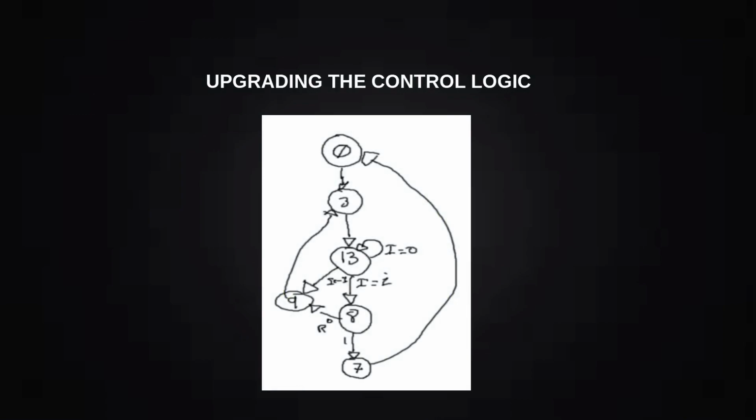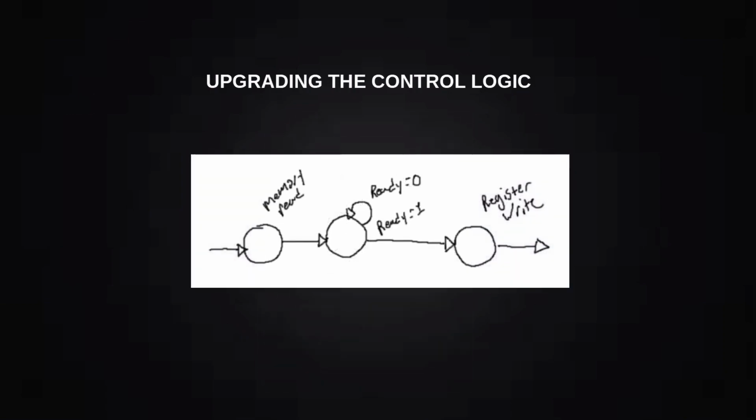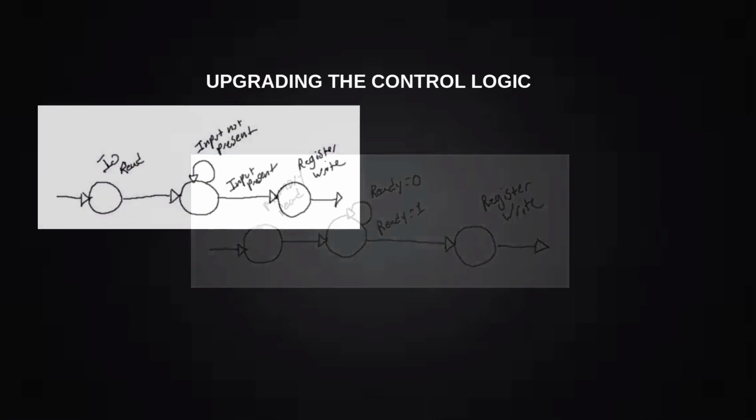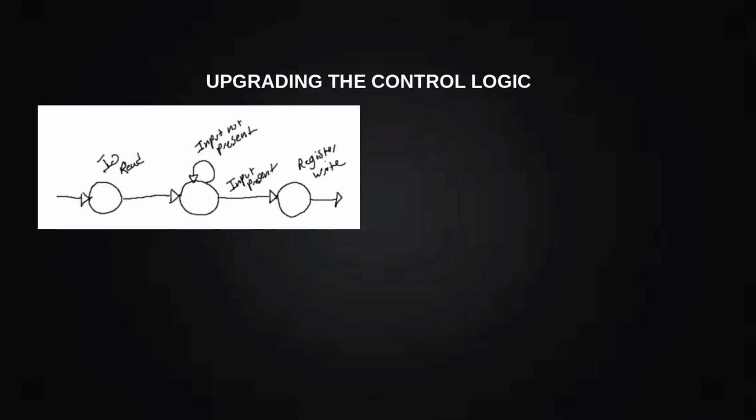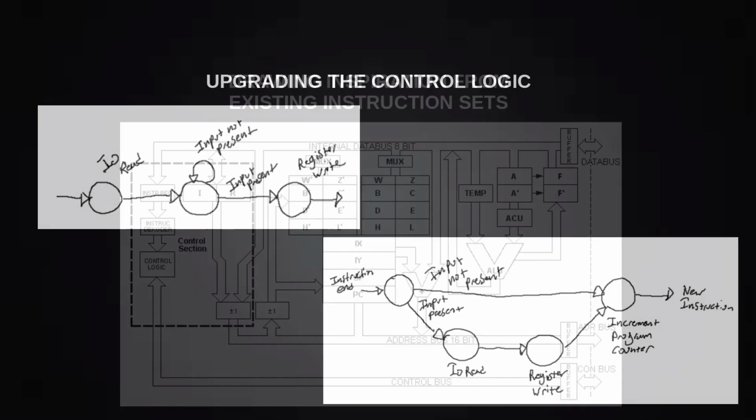Creating a state machine that produces sequences of control signals before giving the signal to increment the counter register is actually a lot easier than you would expect. In fact, loads of new possibilities open up if you use a state machine. If you have a latency issue with RAM, you can have the computer wait for the ready signal before completing a memory read or write instruction. If you want your computer to wait for the user input, or better still, drop everything and respond to the user input immediately, you can use a state machine to bake that sort of behavior into its execution cycle. That's not something I'll be covering in this video, but I'd still recommend playing with the idea.